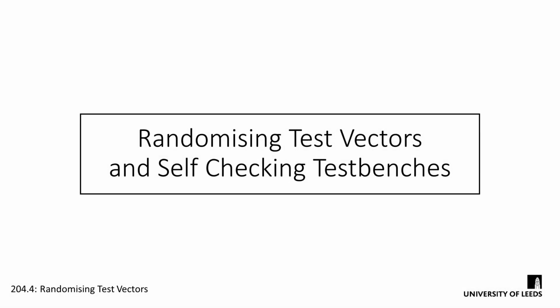Up until now, we've only really tested designs with a small number of inputs. We've been able to validate these designs by generating test vectors for all possible input combinations and verifying the output visually in Modelsim. As we move towards 8, 16 and 32-bit systems, however, this no longer becomes viable. It would take both the simulator too long to run that number of test vectors and us too long to read over that many results. So we need to start getting smart with our testing.